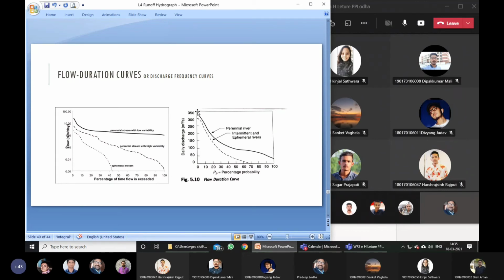So the highest flow during the flood of 2006 was 14,000 cubic meter per second in the Sabarmati, and that too in Paladi area. So 14,000 cubics. So you could assume this 350 mark is a small flow, a small creek meeting a major river. So now understand the kind of flow duration curve.